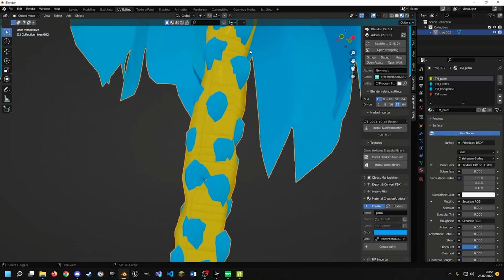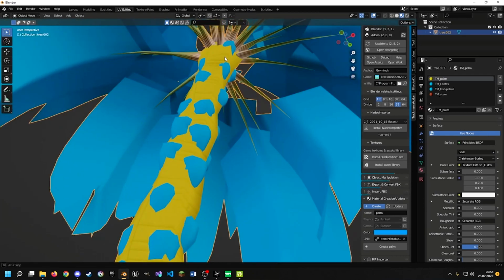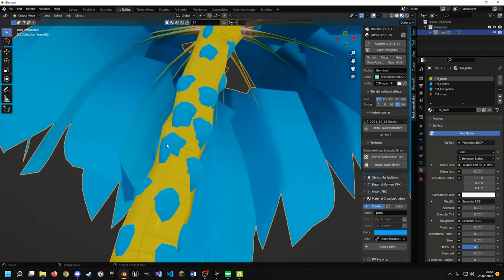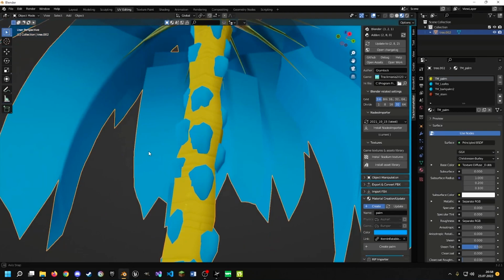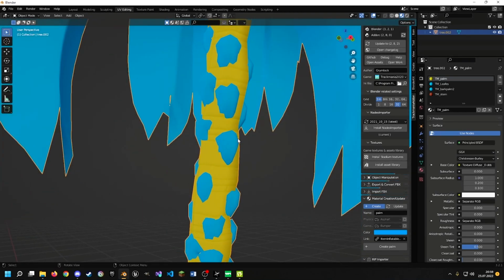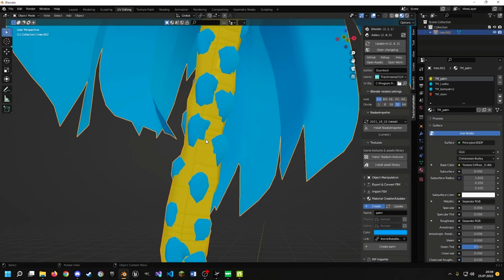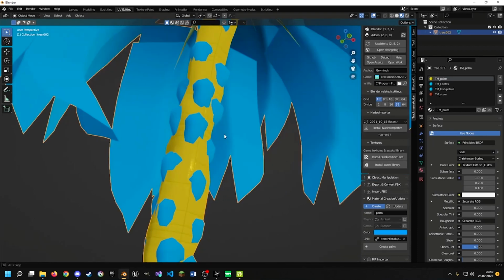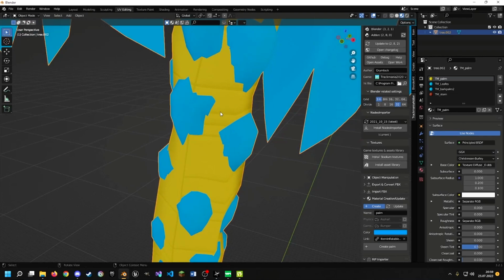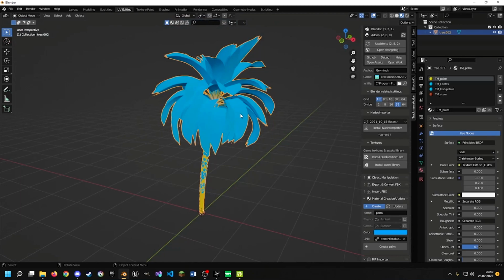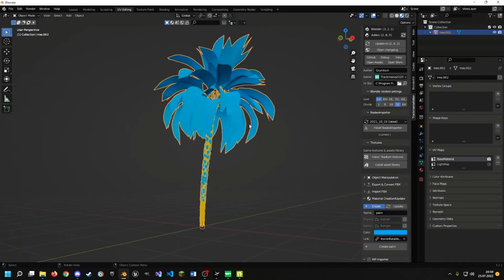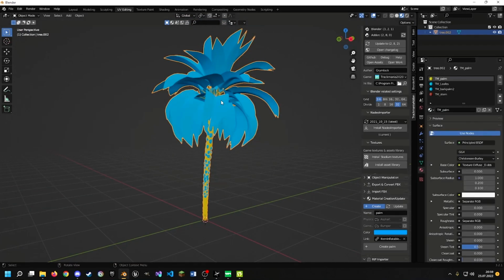I also noticed during testing, I took the cactus material and used it for these spots. And it happened that if you use a specific texture, if the UV is mapped outside of the UV square, you get a really weird distortion and you have to remap it into the square for Trackmania to render it correctly. So basically it has everything done, the materials are done, and the light map is done.